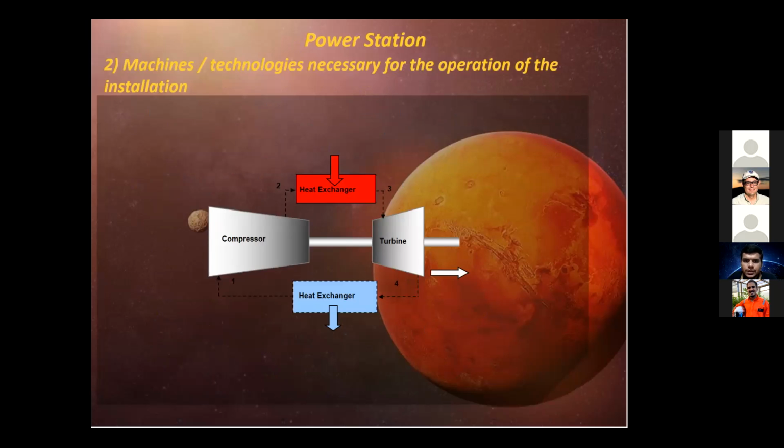So this is the graphical representation of the Brayton cycle. Here is the compressor. This is the inlet of the compressor, where it is written 1. The compressor will be taking the fluid, CO2, from this inlet, and after that it will go to the heat exchanger. Basically, the heat exchanger is a combustion chamber where pressure remains constant, and before that the compressor will raise the pressure to around a pressure ratio of 10.